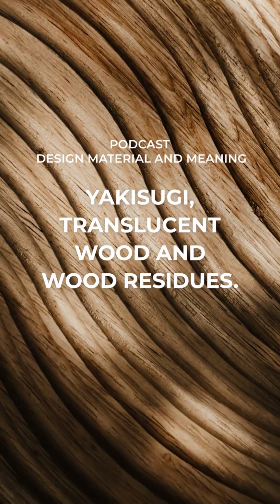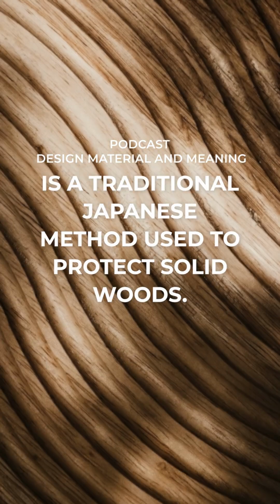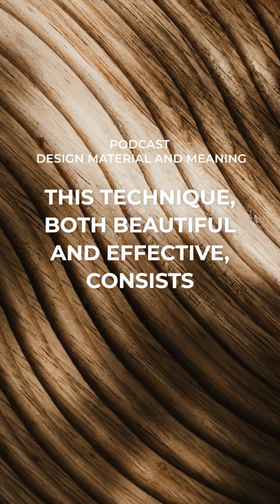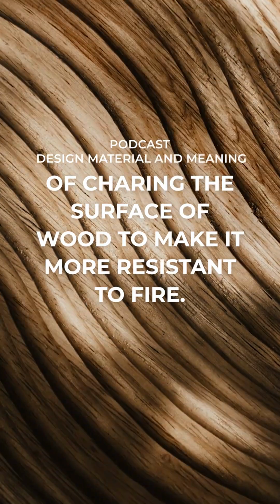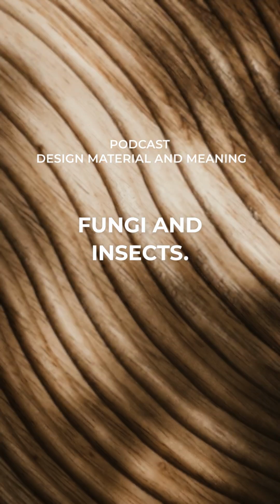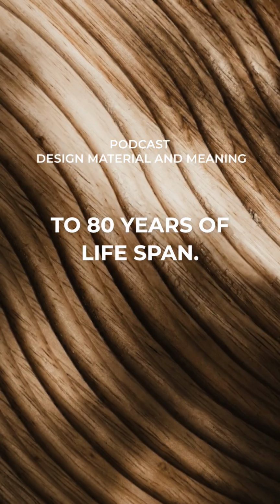Yakisugi, translucent wood, and wood residues. Yakisugi, also known as shou sugi ban, is a traditional Japanese method used to protect solid wood. This technique, both beautiful and effective, consists of charring the surface of wood to make it more resistant to fire, fungi, and insects. Yakisugi pieces can reach up to 80 years of lifespan.